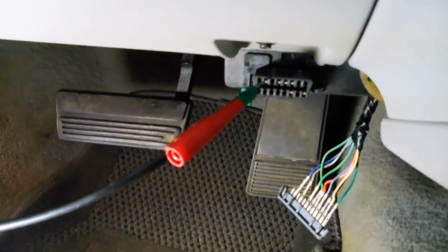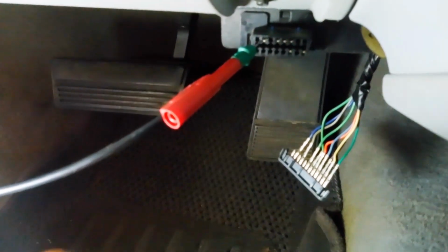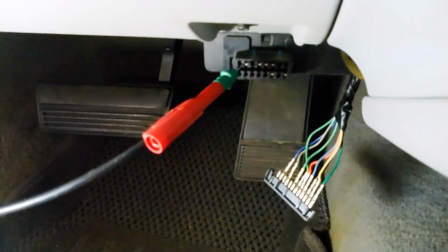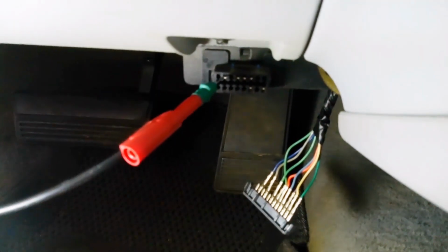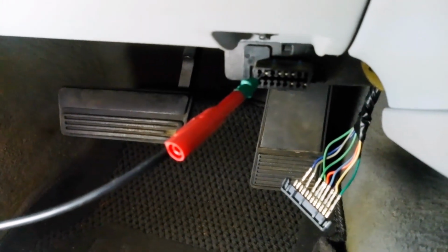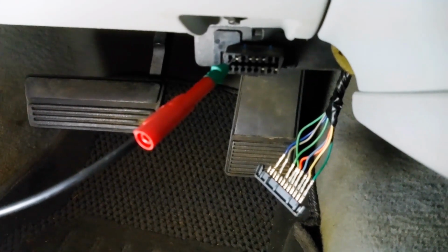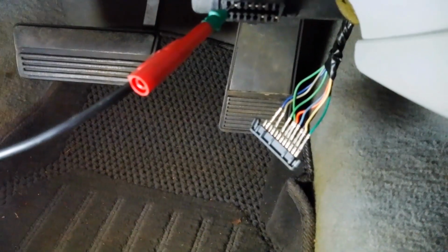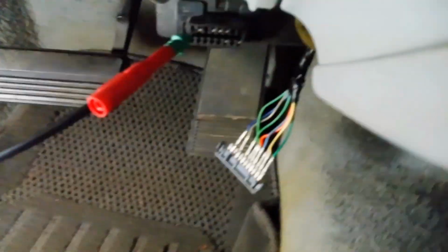Okay, here's the setup. As you can see, I've got my splice connector de-pinned and they're all plugged back into the comb so that I can unplug those one at a time. I have my scope channel 1 on pin 2 of the DLC. That is our purple wire that runs down to that splice connector there. So we're tied into that splice connector. We can de-pin these as we want, one at a time.